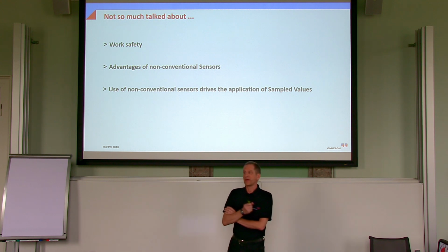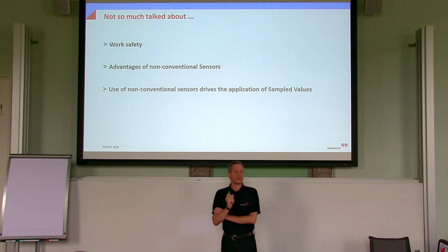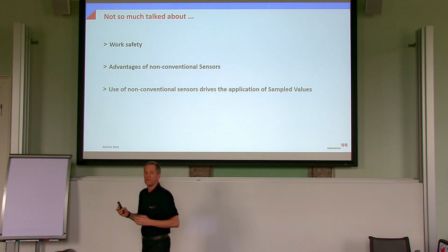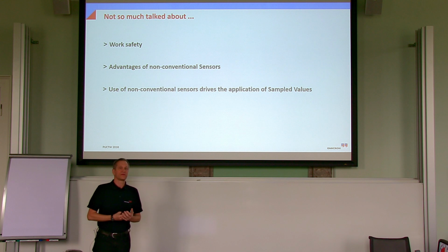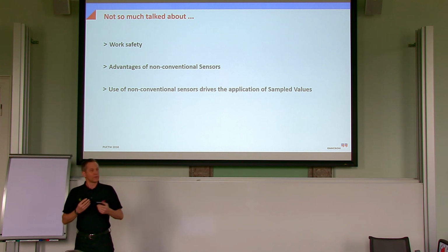And bottom line, they are a driver for this digital substation, because all of these non-conventional sensors have interfaces which are not interoperable. The only interoperable point is at the output of the merging unit, where we have a standardized protocol where we can again combine sensors from different vendors with devices from other vendors to communicate with each other.